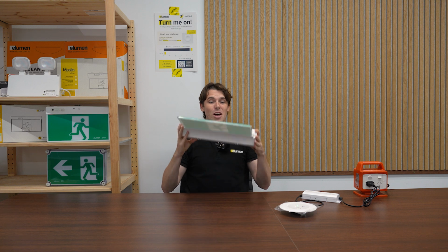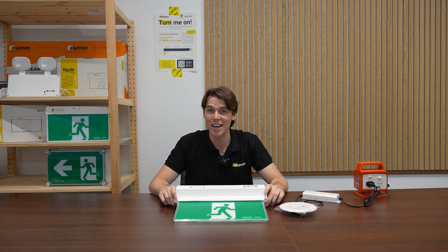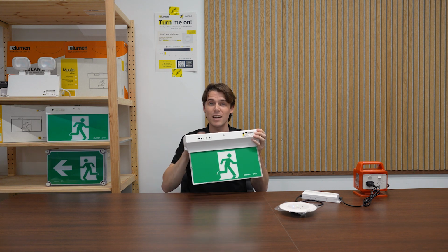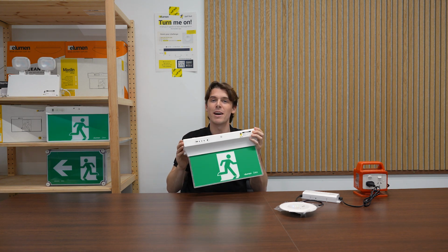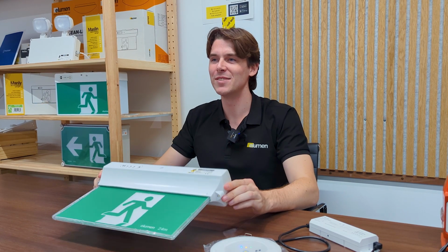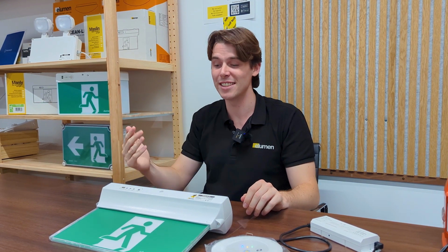That's right. Automated systems only need to be connected to the nearest hard active circuit, because each luminaire has its own timer and switch that manages its discharge tests. This makes automated systems ideal for heritage sites, as you don't need to punch through asbestos or sandstone in order to wire in a dedicated emergency circuit. You can just attach it to the closest hard active circuit.